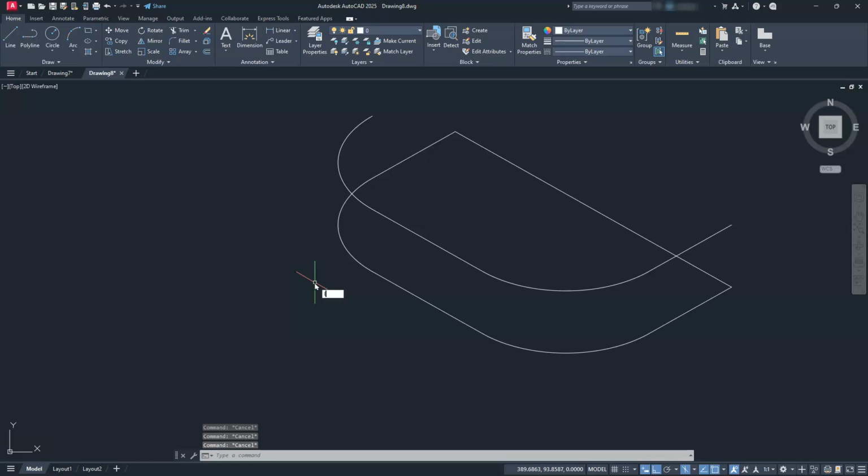All right, let's draw some lines to kind of connect this. So I'll draw a line from here, going down. And then I'll select this line, and I'm just going to copy it, right? So I'll select here, the space bar one time, select the word copy. And then all I'm going to do is place at that endpoint, this endpoint here. I have an endpoint here, and then I should have a quadrant to locate it here.